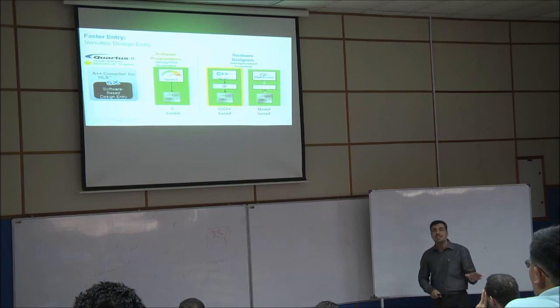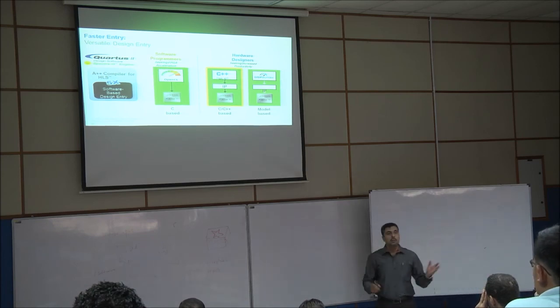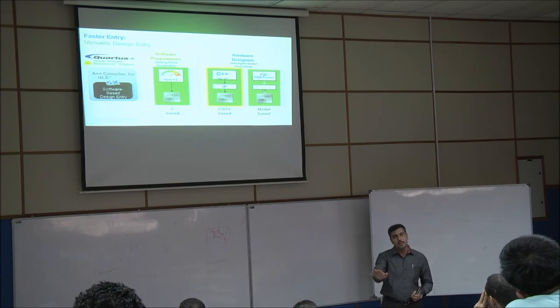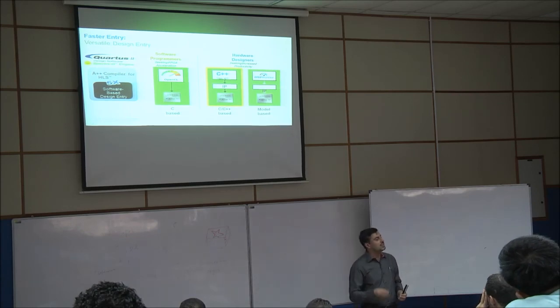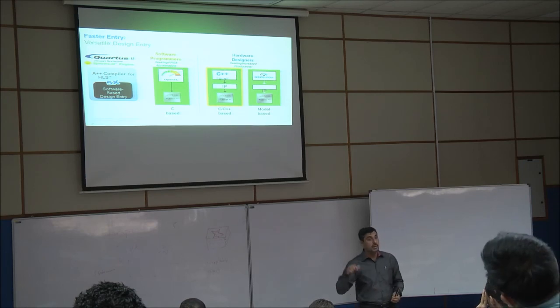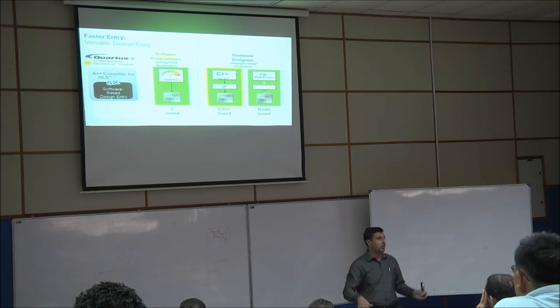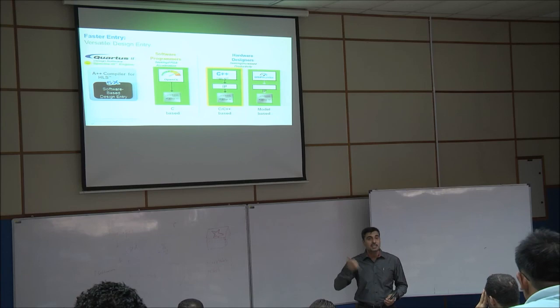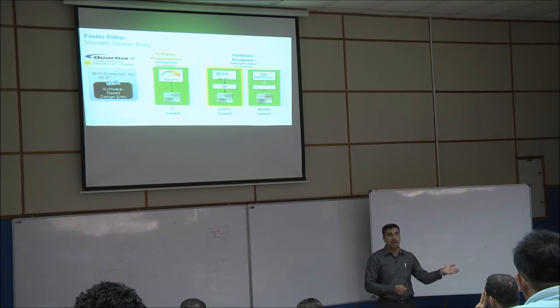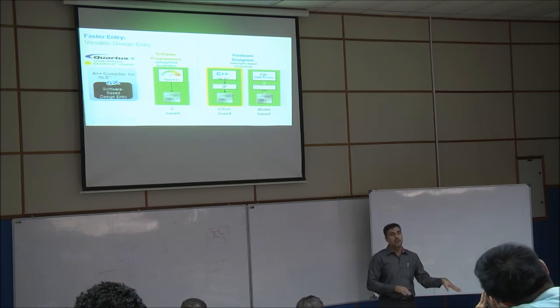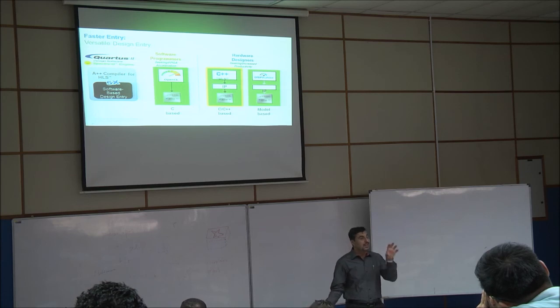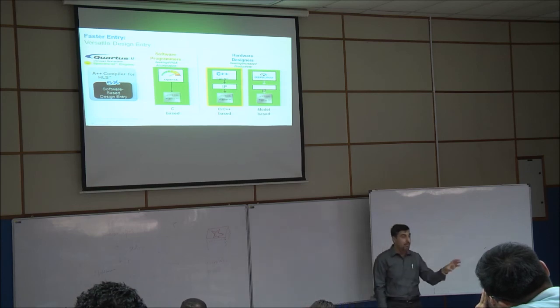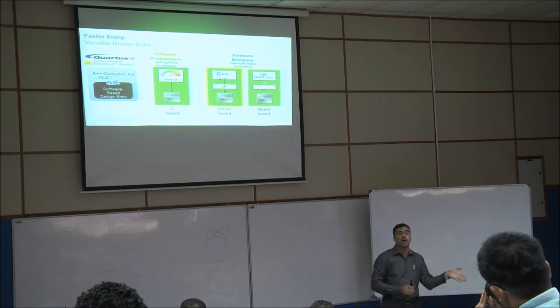DSP Builder is for those not in computer engineering, who don't know or don't want to do any programming. Very easy. They give you DSP Builder or System Generator. In Xilinx they call it System Generator, and I'm trying to explore both technologies for you, Xilinx and Altera, I mean Intel. Xilinx calls it System Generator, while it is DSP Builder in Intel FPGA. If you know MATLAB and you install DSP Builder, you will get some module blocks inside MATLAB. We can see the sign on each module is related to FPGA.